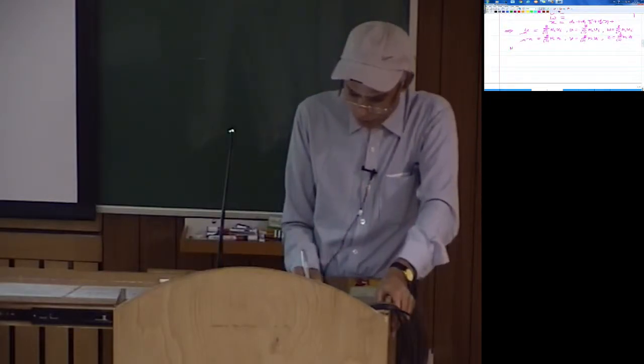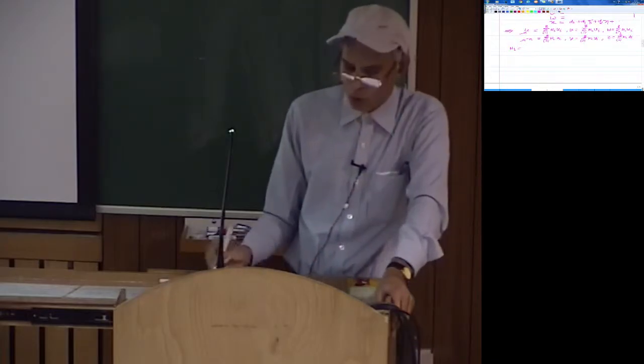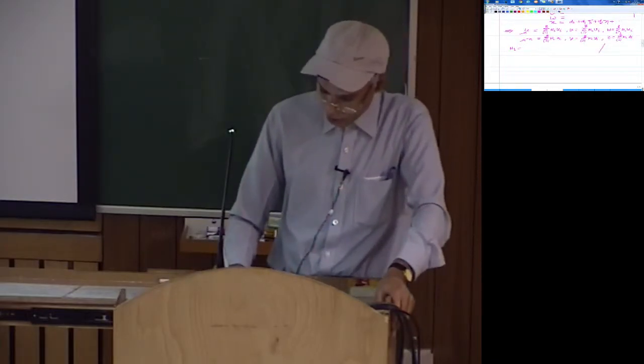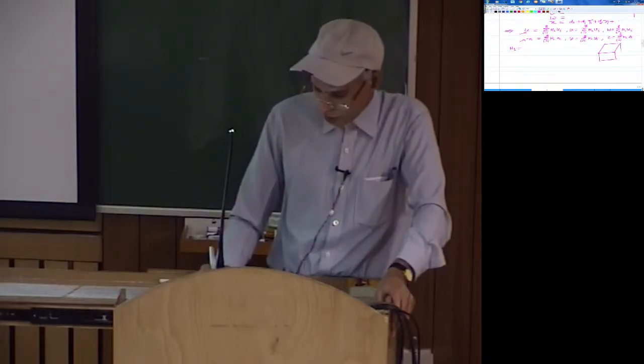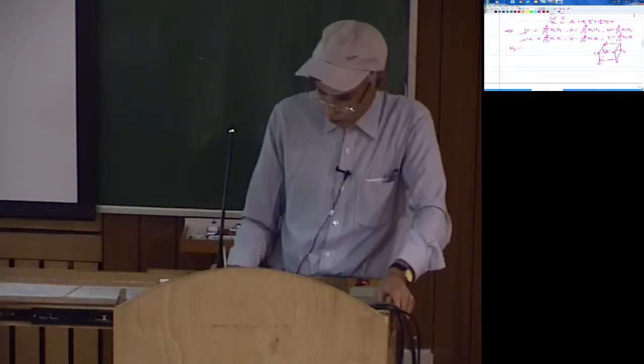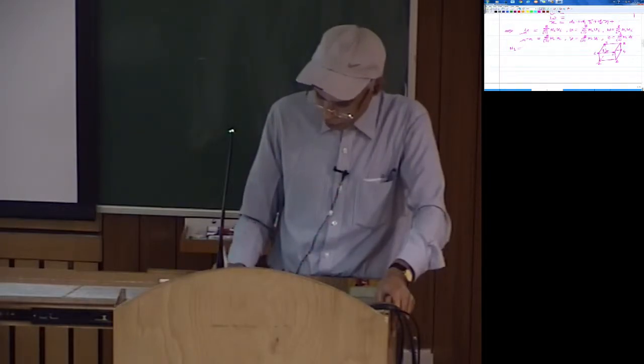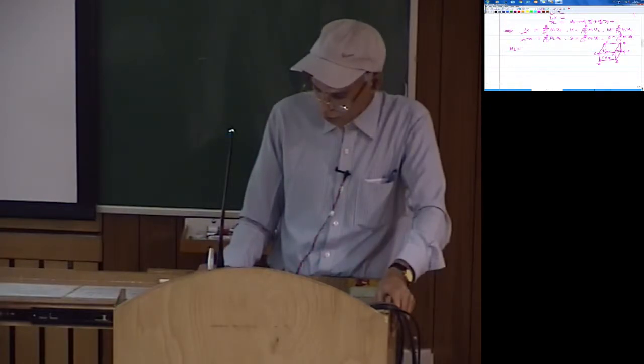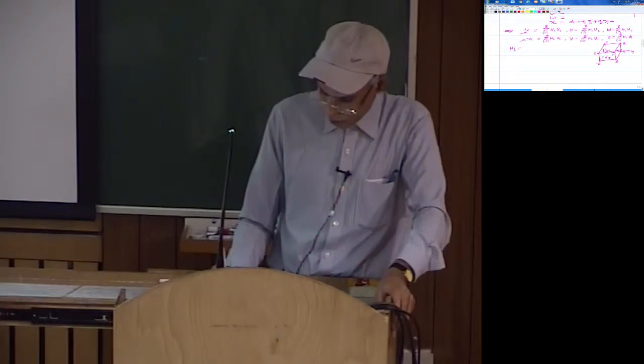So now if you look at the procedure I described briefly, the expressions for these shape functions, say for example N1 corresponding to the first node. Let me sketch again rather than going up and down. This is the element in the natural coordinate space, and this is node 1, node 2, node 3, node 4, and node 5, 6, 7, 8. This is your xi going up to the centroid, this side is your eta, and from here this is your zeta.